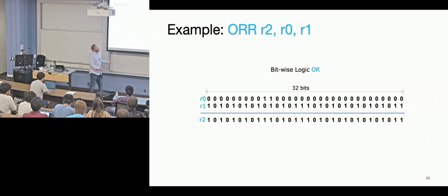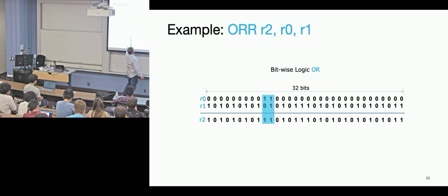It's much nicer if you can just do a bitwise OR. So you can just take the register that's holding the output state, take that in, and take your mask, the bits you want to add to it. So here I want to add 1 and 1. You OR them together, and now all that information is retained. You didn't have to do any calculations on it. You didn't have to hold the state. All that information is retained, and here you've gone and updated one of those bits. Okay, so that's an easy way to not worry about somebody else's code and what they're doing with those LEDs.